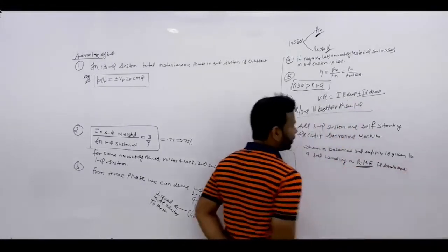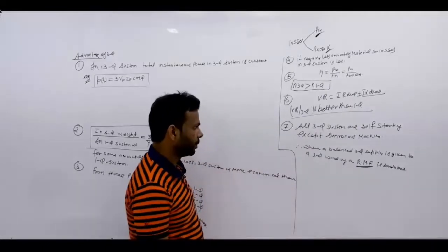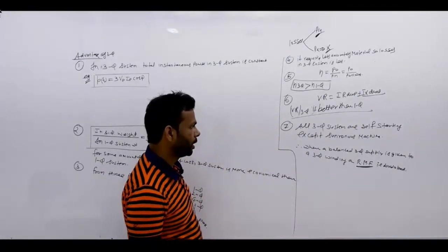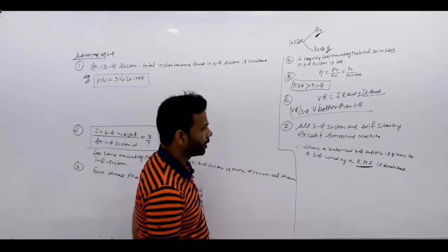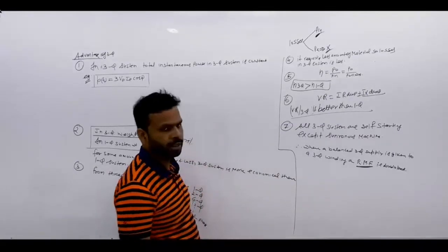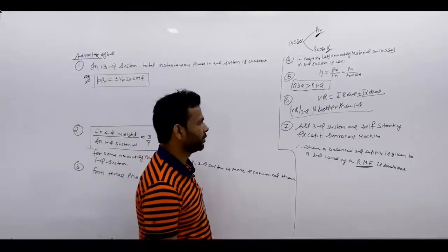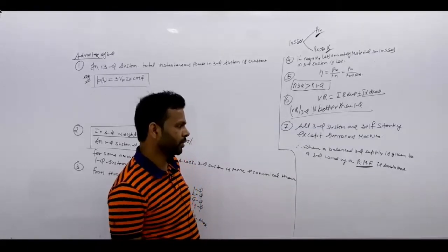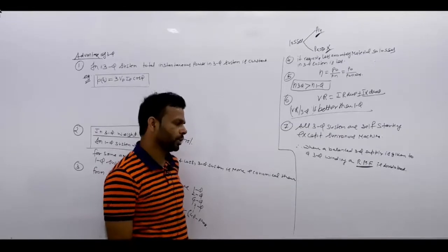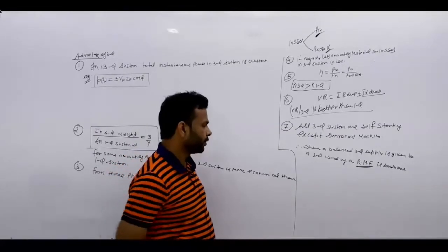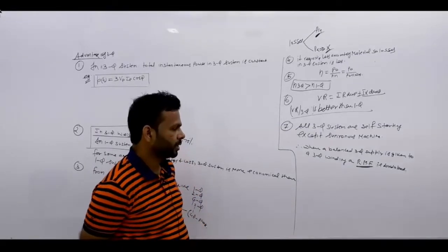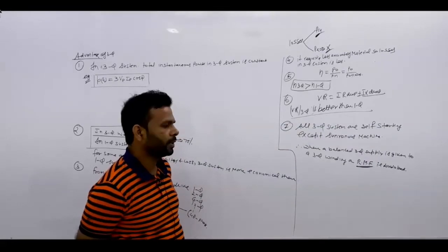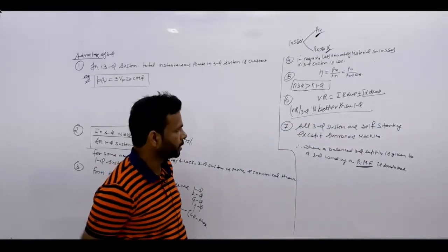When a rotating magnetic field is developed, your machine is self-starting. But all single phase machines are non self-starting, like the single phase induction motor. Then you require the phase split method, capacitor start, capacitor run. Different methods are available for that.